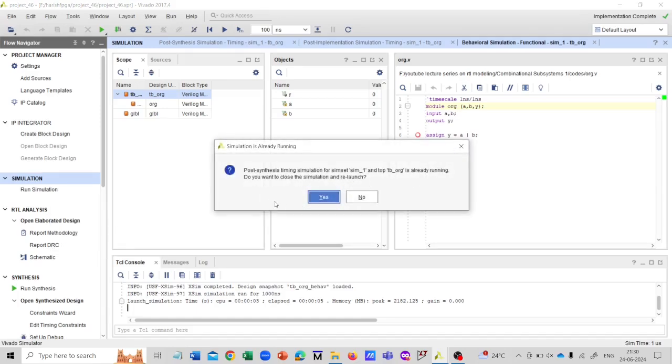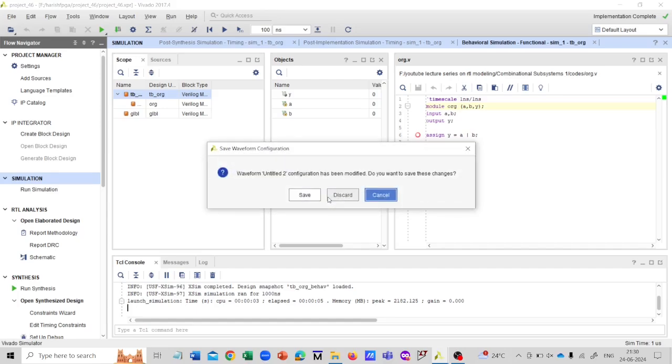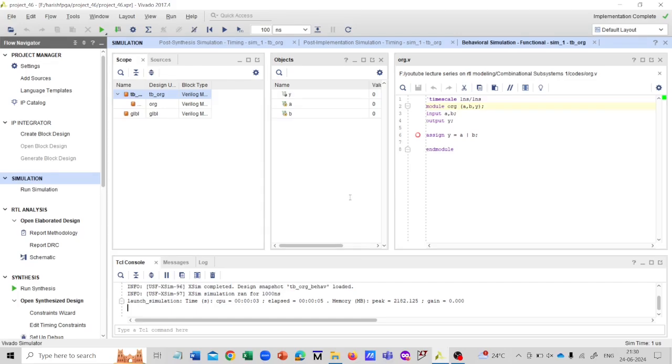Of course, the synthesis process has several subphases. We will not go into all those details. First, the design is targeted to a set of generic gates, and then it is further subjected to another process where it is translated into the FPGA LUTs and so forth. Anyway, let us not go into the details of how it is done, but let us see what happens when the post synthesis simulation is carried out.